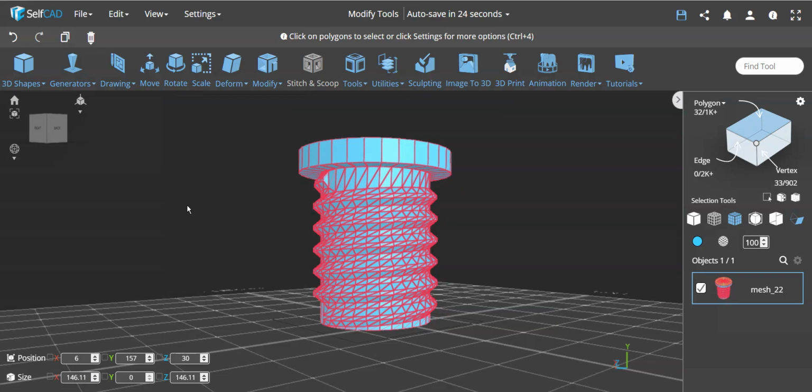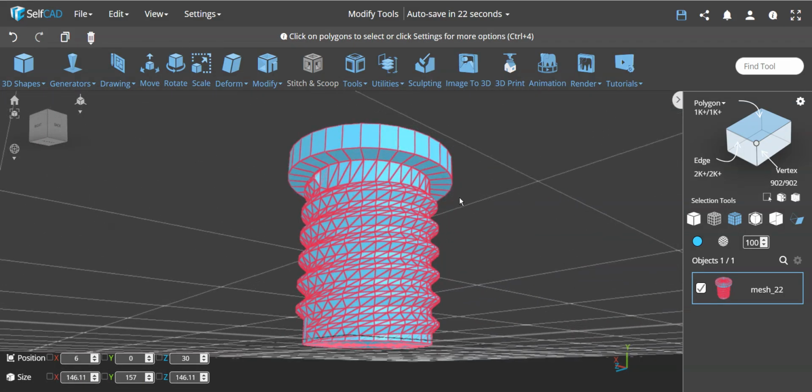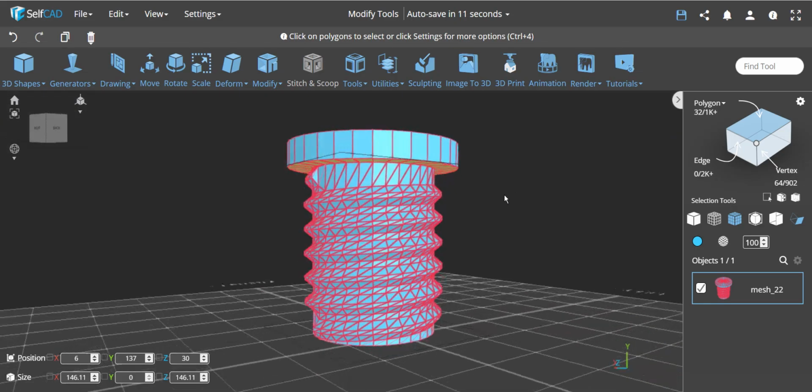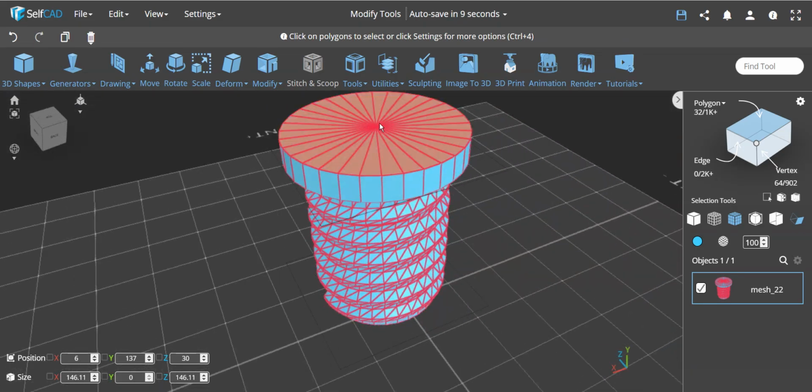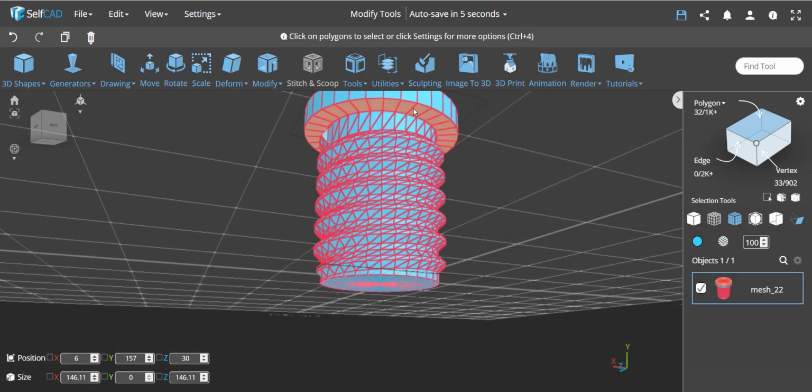this actually creates something like this. So let me explain what happened. When I did the first extrusion, it added this face over here, just sideways. And this sideways by itself is not doing anything. It's just overlapping on top of the other face and extending. It's not manifold. But once I move this up to create this, actually this face was created initially. This was the face that was created, and it was laying over here.